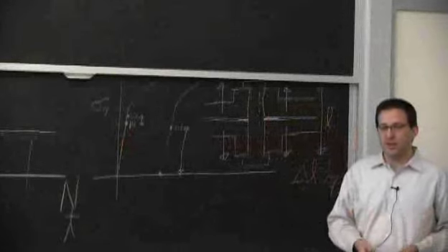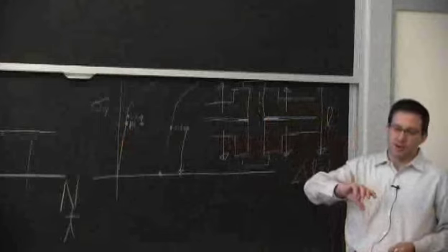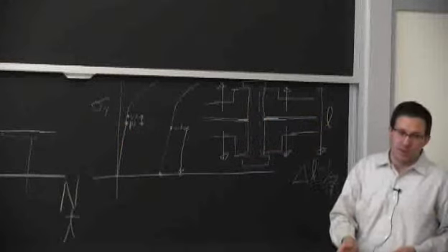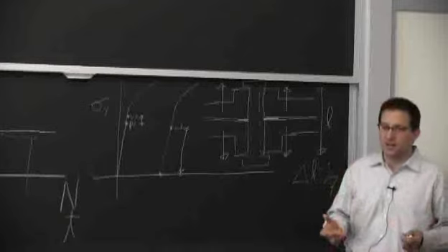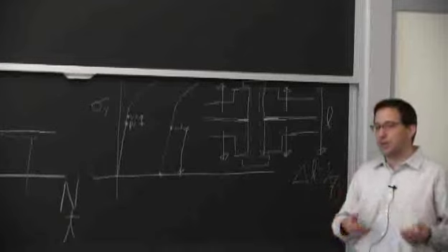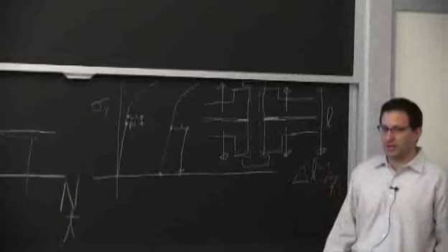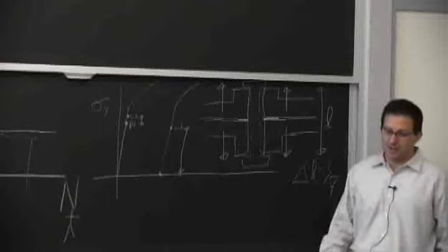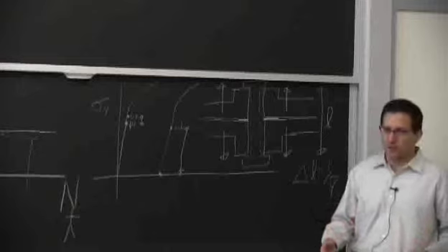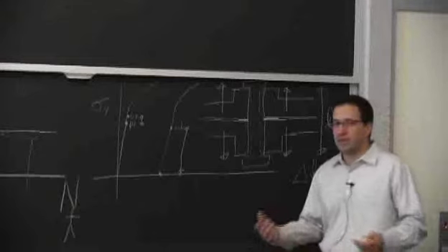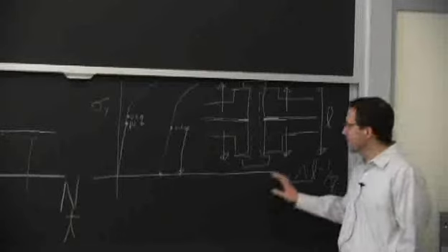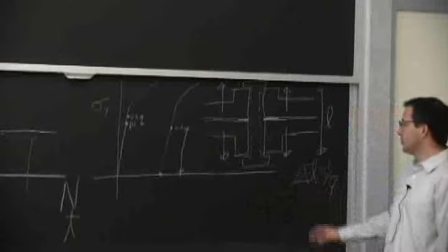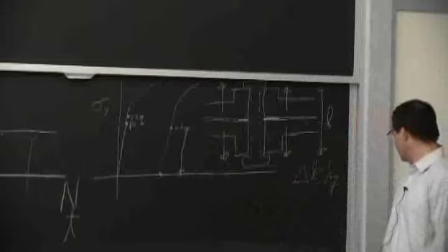You can ask for a specific torque. You can ask for a certain number of turns to load the bolt, but it's not super precise. So you do need a good safety factor associated, but you're giving yourself a chance as opposed to having loose bolts, essentially. So that's kind of what we talked about, but maybe presented in a more summarized way.